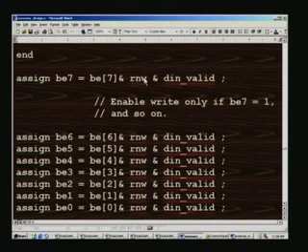So whenever we are in write mode, only then this should be computed, and all of them are assign statements, therefore they have been declared as wire earlier. Data in is the one where we input the data, and the corresponding valid signal is this one. So unless the signal is valid and unless it is in write mode, we should not write into that, and this is just a preparation, merely a byte enable done in this fashion.